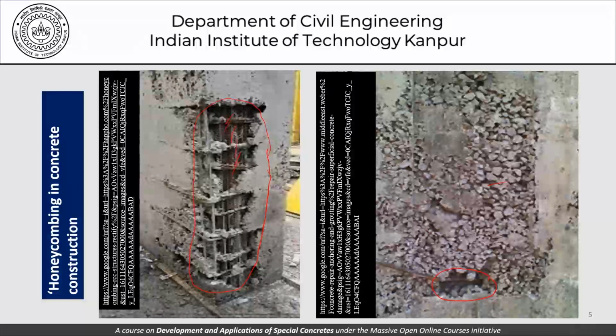But from the science point of view, what causes the concrete to move into all these places, either on its own weight, in which case it becomes self-compacting concrete, or on account of the application of vibration or during compaction of that concrete, carrying out external work as far as that concrete is concerned.